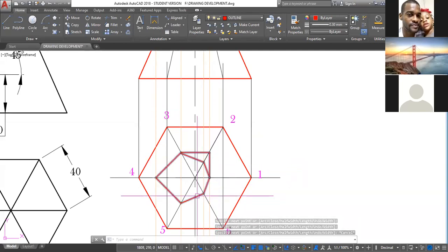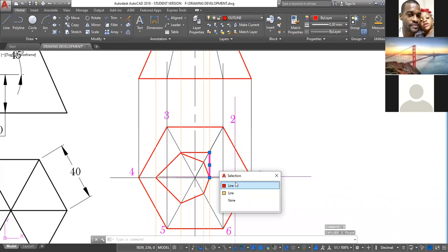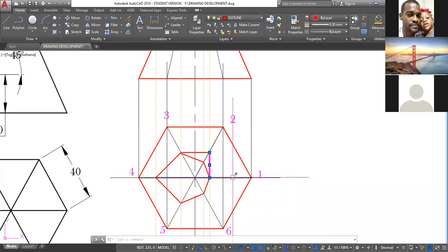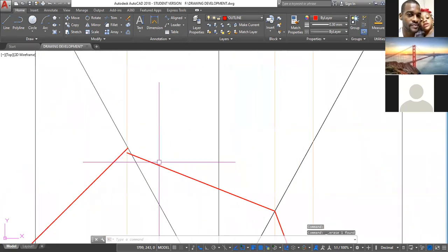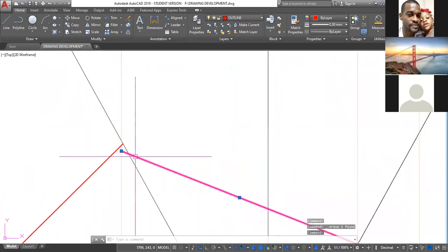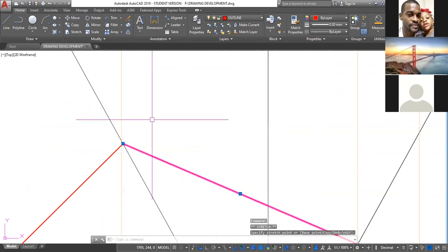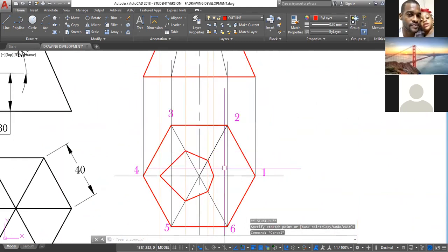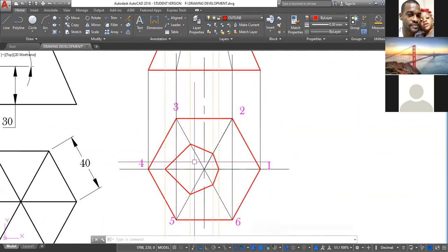So I need to explode this, X, enter, to be able to delete these independently. Enter, delete. And this line doesn't touch precisely. Grip, move in place. We have that. So now we have the cutout section. All of here is the cutout.